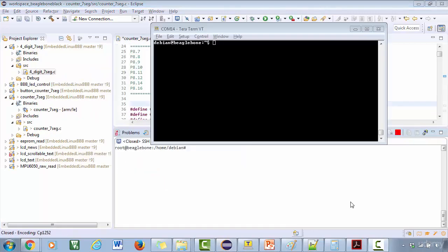All right, so I just did a connection here. I didn't do a full connection. I just connected 3 wires here. The first wire is this one, which is connected to ground. This is the 3rd pin of the 7-segment display, which I need to connect to a common ground. So this is a ground wire, and then I have connected 2 wires to 2 different segments.